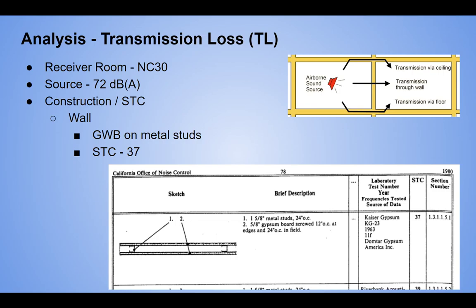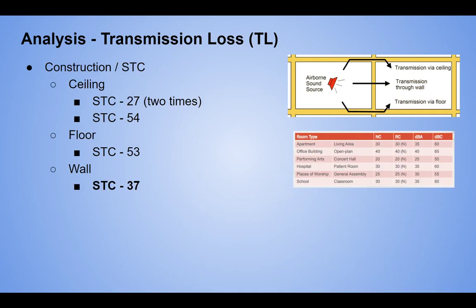Now, if we look at the wall, we couldn't confirm it, but we're going to go with the basis that this is a lower end fit out. Let's say it's a mass produced housing aspect, and they wanted to save money by spacing out the studs and making them smaller. So they're at 24 inches on center, and they're 1 and 5/8 inch studs. That gives us an STC of 37. So that's kind of lowest. That is the lowest common denominator, and we need to get that to 42. We're only off by 5, but that 5 could be a big deal, as we're seeing.